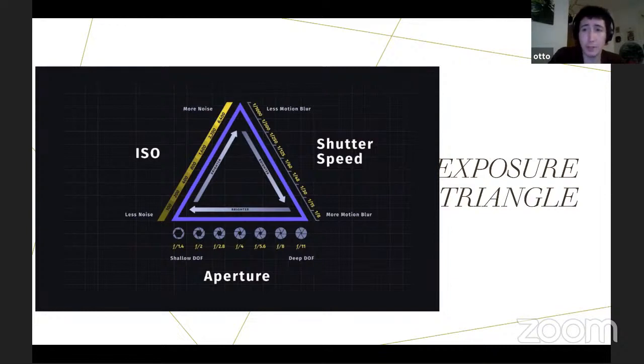In museum conditions, it's often quite easy to mitigate that because they tend to have rather good lighting conditions and you can control the light very well. But when you're outside recording a building, for example, this is way beyond your control. So you need to carefully plan your recording session and keep an eye on the weather, because even a cloud passing over the sun makes the light more diffuse, which is a good thing, but at the same time it also makes everything much darker. So you have to slow your shutter speed right down.